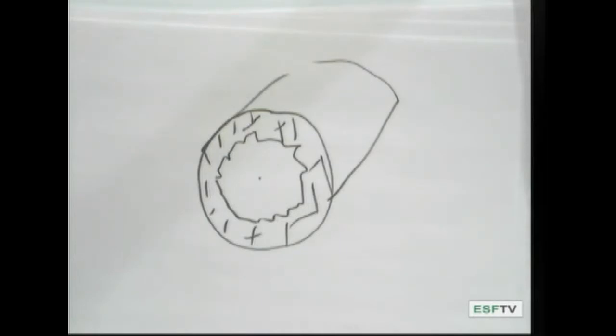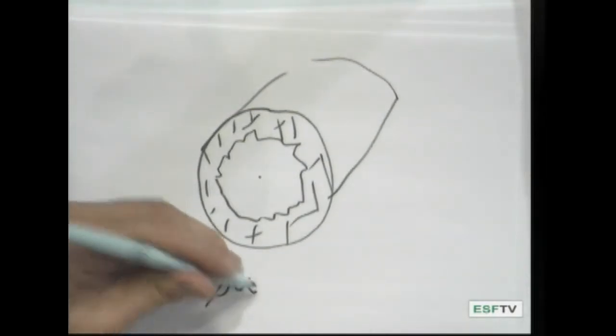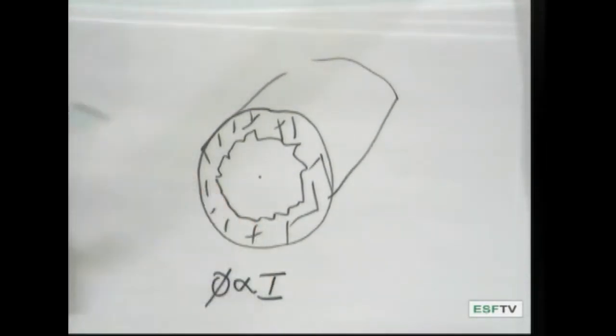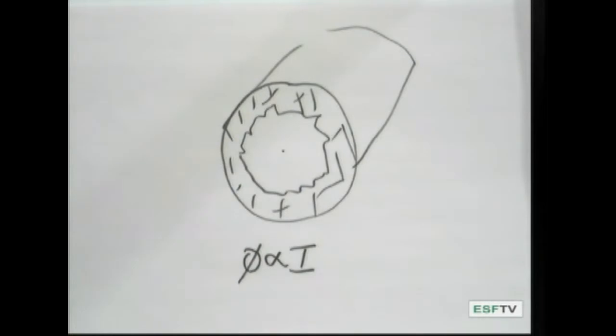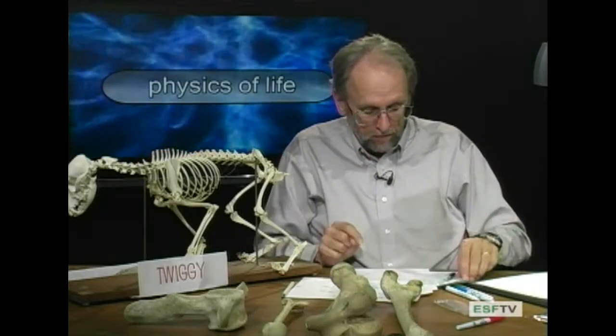Now, where this comes into flexural stiffness is that the flexural stiffness of an object is also directly proportional to the second moment of area, which we symbolize as I. So now we have three things that feed into the flexural stiffness of an object. We have the length of the material, we have the Young's modulus of elasticity, and we have the second moment of area. And what we can do is calculate a formula.